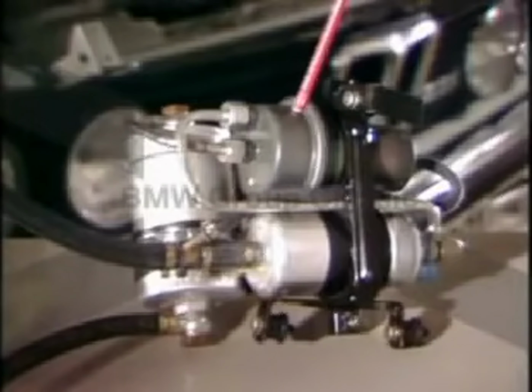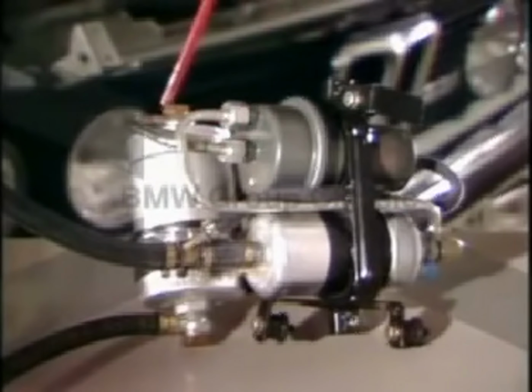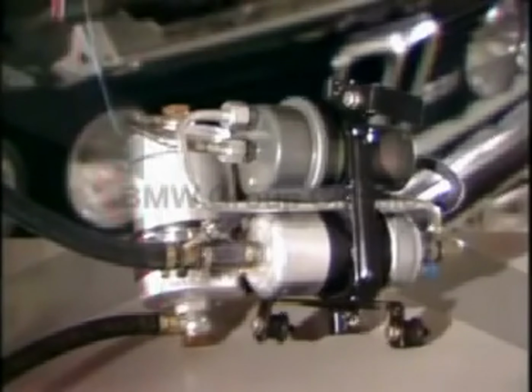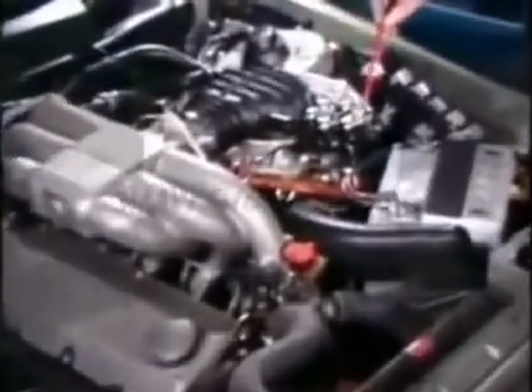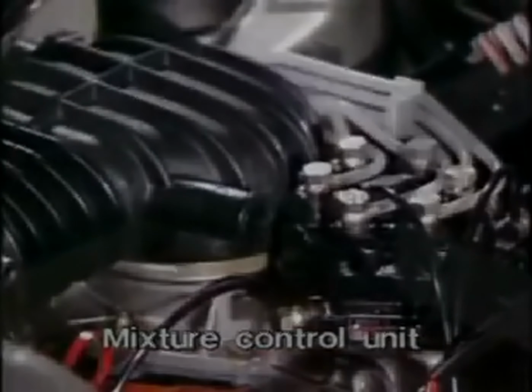This inhibits the formation of vapor bubbles and facilitates trouble-free hot starting. Fuel is directed from the pressure accumulator to the fuel filter. From there, the fuel is directed to the fuel distributor in the mixture control unit.